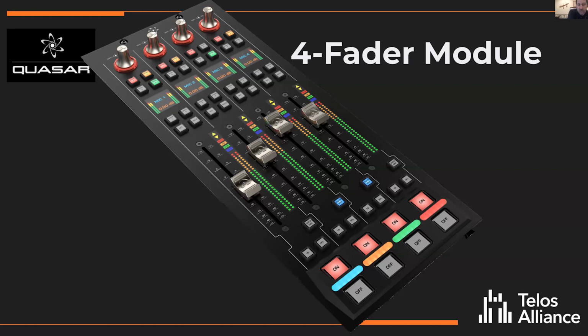And then you have a network connection. In fact, the bottom of this module has 2 network jacks. So if you really wanted to be redundant, which is one of the things customers were asking for, more redundancy in our flagship products, you can run 2 Ethernet connections to this module, a main and a backup. Cam, I believe you can also daisy chain the Ethernet connection from one to another, yeah? And that would be the other functionality of that second jack: if you wanted to save some space on your Ethernet switch, you can go from the switch and then daisy chain across all the modules and complete the circuit that way as well.